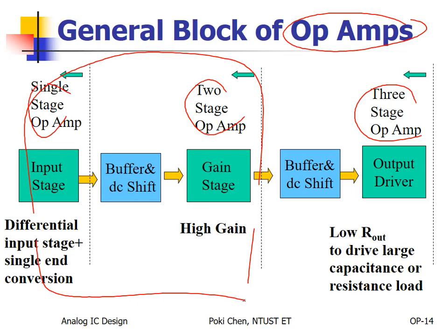Okay, we don't amplify the voltage for more than two stages. Why? Instability. Later, if I have time, I will show you this. More than two stages usually means unstable. It means even if you apply very strong negative feedback, you still cannot make the overall system stable. So I need to warn you. One or two stages for voltage amplification should be good enough. No more than three. Okay, no more than two.